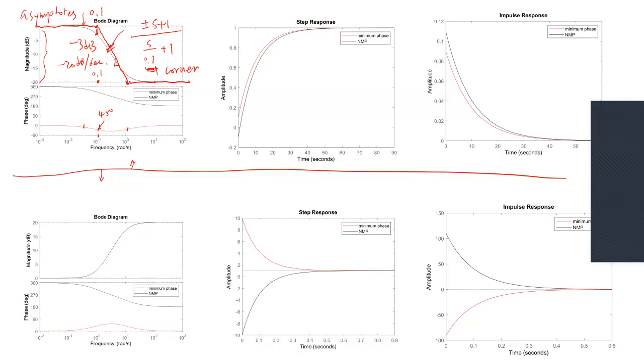This small one here is a minus 3 dB, okay? And this corresponds to here, so this is 0, this is also 0. So this is 45, this is also 45. So it's a lag filter, okay, lag filter.